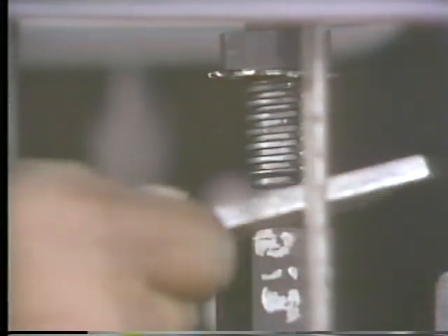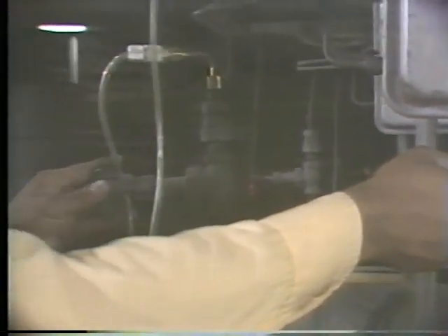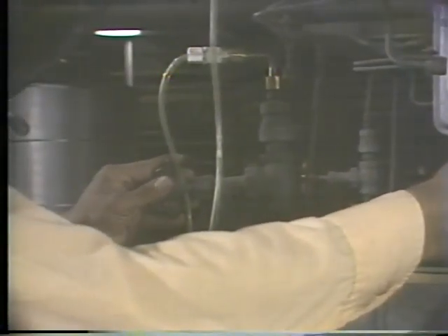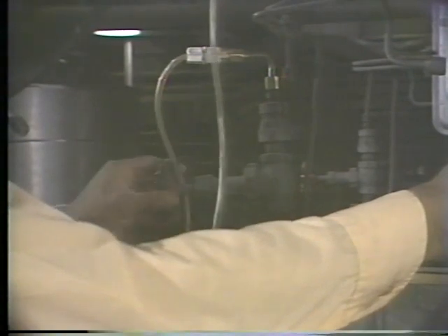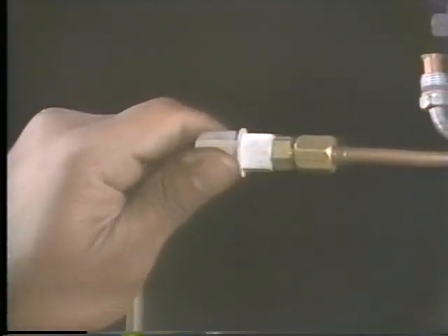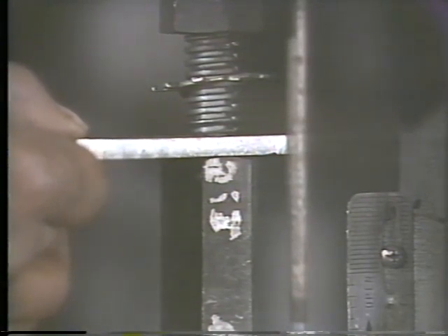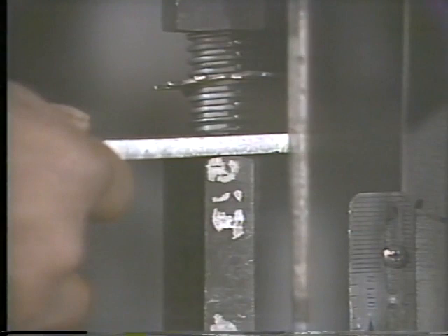This is done by, first, placing a flat metal bar between the hex nut and the actuator stem. Then, shut off the air to the actuator and remove the air line to unload the air inside the actuator. As the air is unloaded, the actuator spring pushes the actuator stem down onto the hex nut, pushing down on the valve stem and seating the valve. Then the air is reapplied to the actuator so that the actuator stem is completely raised to the open position.